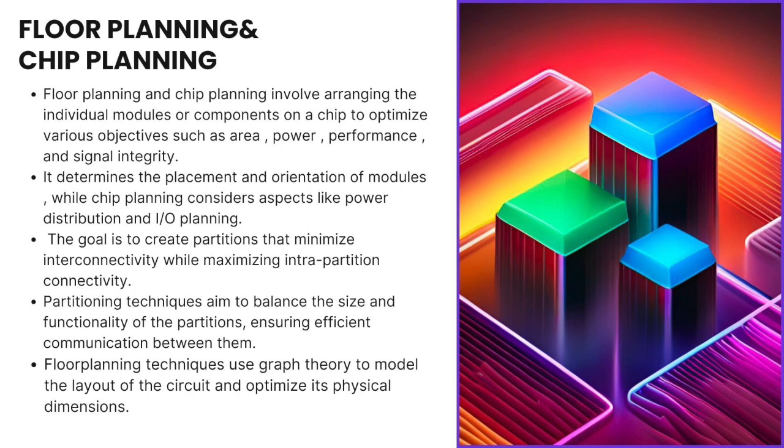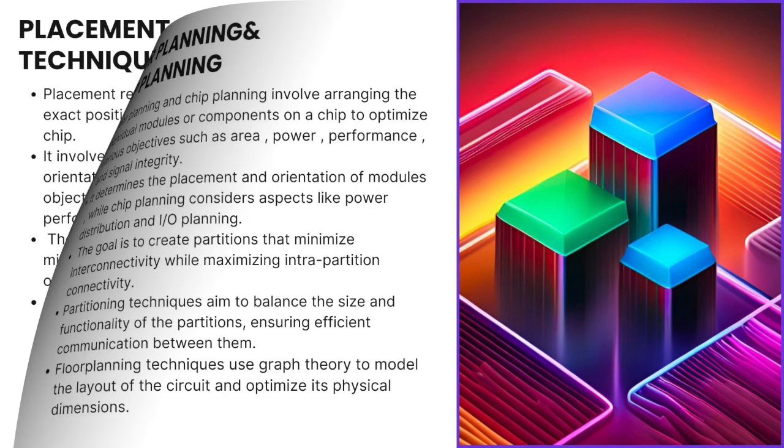These sub-circuits are used to form modules, and these modules are used in floor planning techniques. As we have seen, partitioning techniques aim to balance the size and functionality of the partitions, ensuring efficient communication between them, while floor planning techniques use graph theory to model the layout of the circuit and optimize its physical dimensions.